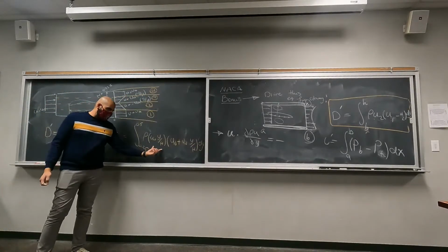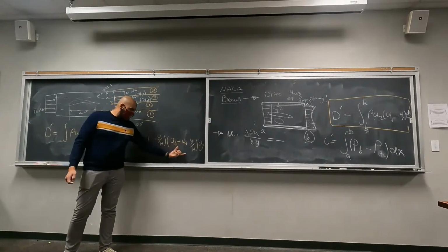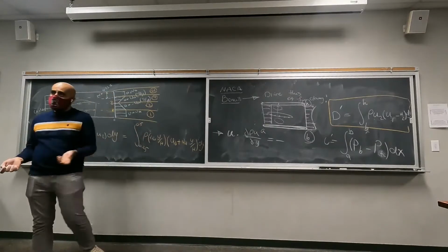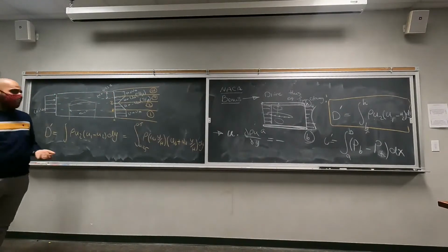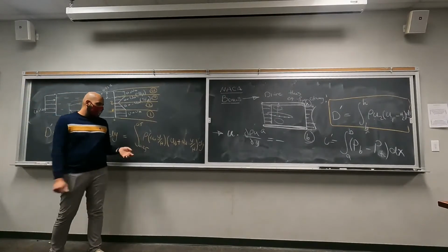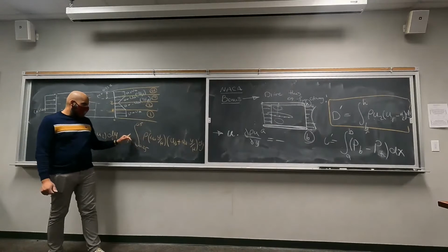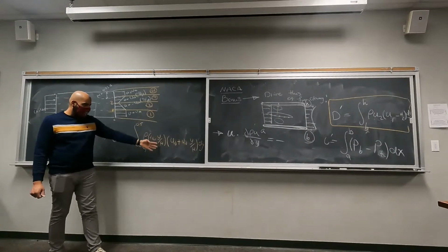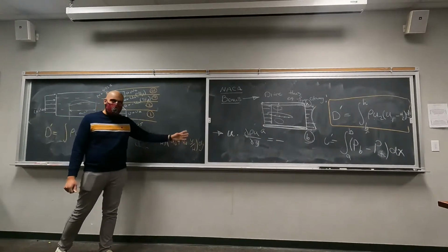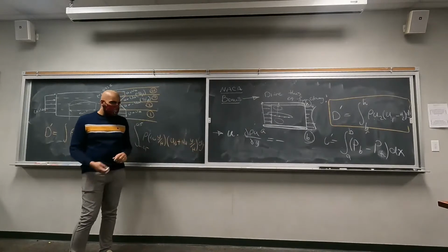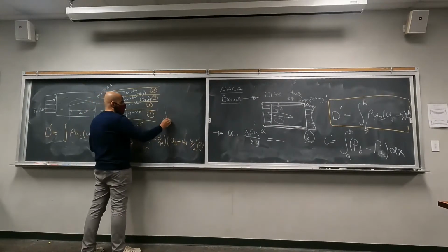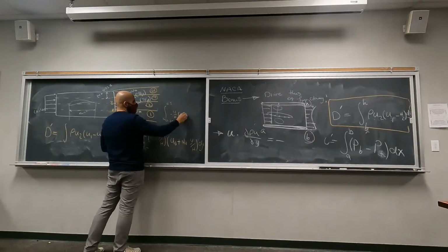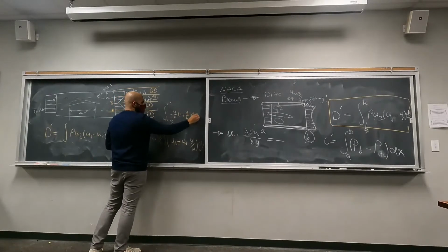You can multiply these two parentheses together. U infinity and rho are constant if we are dealing with the incompressible flow. Rho is constant, so we can take all of these out. We're going to end up with rho u infinity squared, right? Because we can take u infinity from here as well. Negative y over h multiplied by 1 plus y over h. Does this make sense? So I'm just going to write this here, 0.25 to 0.5, negative y over h, 1 plus y over h, dy.